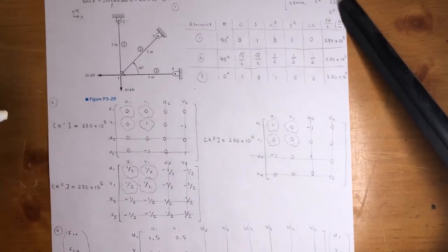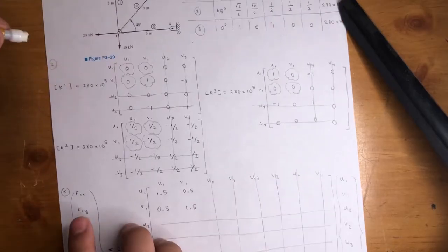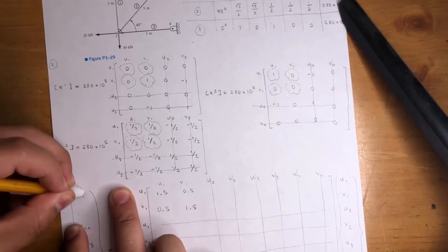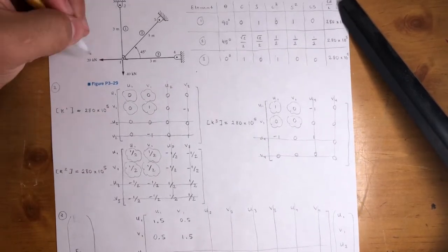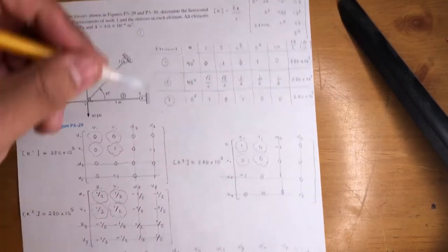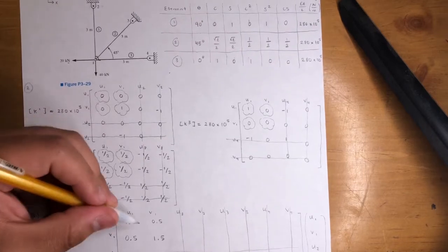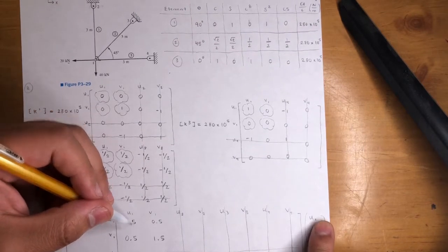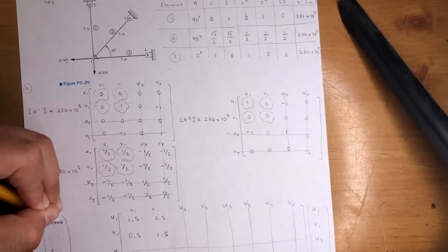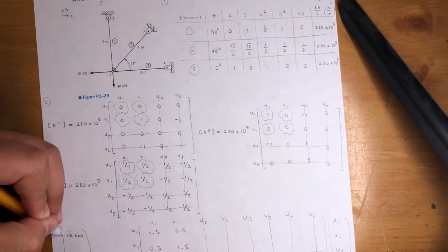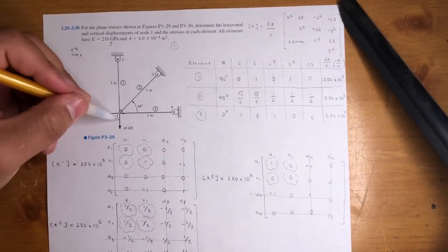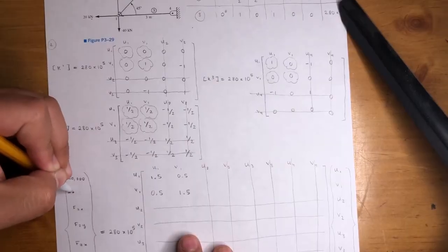So cool. And we also know the force acting at node 1, so we could go ahead and replace these numbers right here. In the x direction, we got negative 20,000. We want it in newtons, not kilonewtons, because this matrix is newton per meter, and this will be meter. Multiply them, you'll get a newton. So you need to convert this. 20,000 to the left, so it's negative. Okay, negative 20,000. And then here we have negative 40,000. We're going down, so it's negative 40.